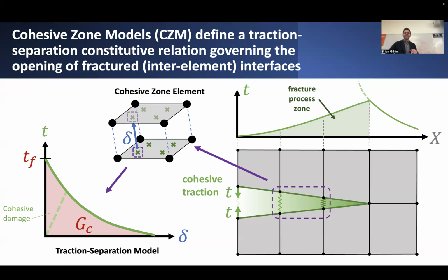So it's like this spring, or the extension of this spring, which initially has 0 length, and I'll denote its relative displacement as this lowercase delta symbol. This displacement governs effectively how much this traction will have to degrade over continual opening as the crack continues to grow.